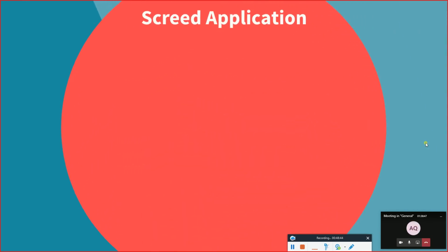Screed application. So we are going to go for screeding or mortar, and this screeding is normally done wherever we require tiling. So if you require tiling, we normally require screeding or mortar. Okay, and you can see here they have tried to make it not totally flat, so that it will stick more. If it's perfectly flat, it will not stick much, especially if it's a wall. Okay? Because the weight of the tile is going down.